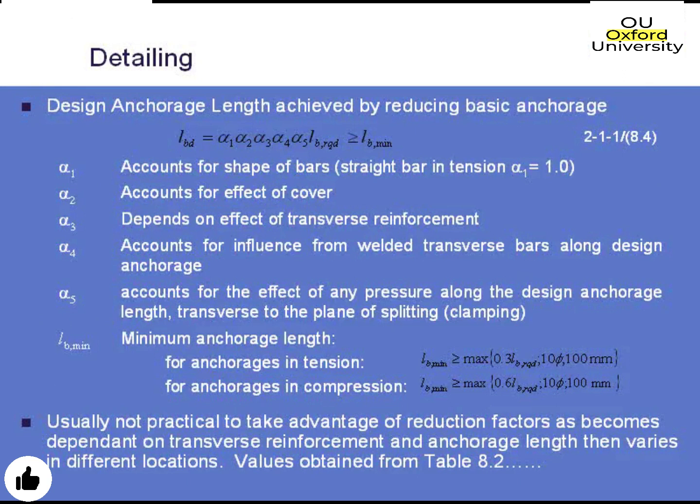The only other thing I'm going to say on this slide is that you've also got some minimum anchorage length requirements depending on whether your bar is in tension or compression. And again, those are just shown on this slide here. Generally, to have the minimum anchorage length applying, you will have had to do a calculation where the stress in the bar is less than the yield strength of the bar, so the bar isn't fully stressed.